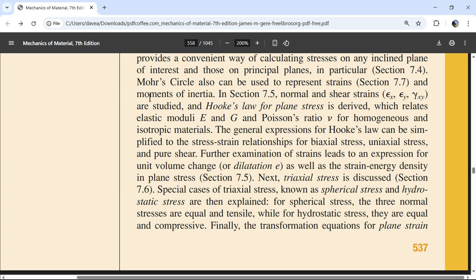And if I take that 1-inch bar to be 1 meter long, or 1,000 millimeters, I know it can only stretch 2 millimeters in length. That would be 2 divided by 1,000, a change in length divided by length of 0.002. So modulus of elasticity says if I have 58,000 psi over here and 0.002 for my change in length per length, E relates those. So what times 0.002 is 58,000?